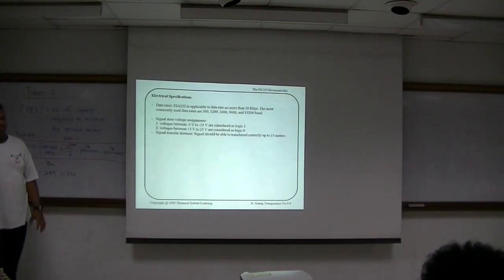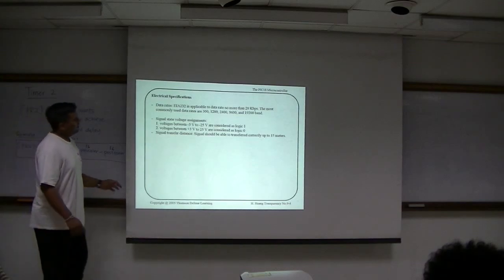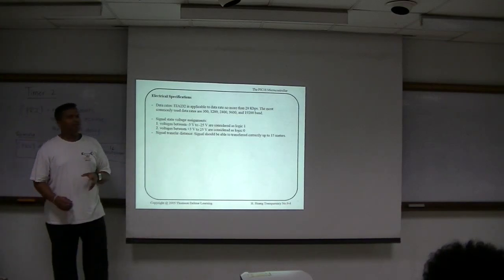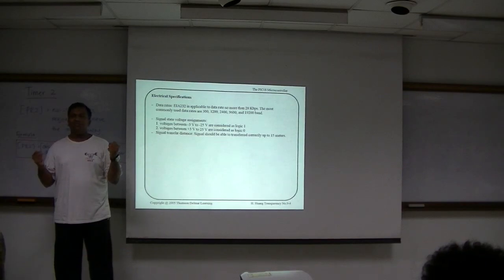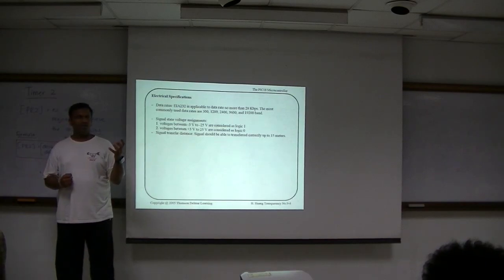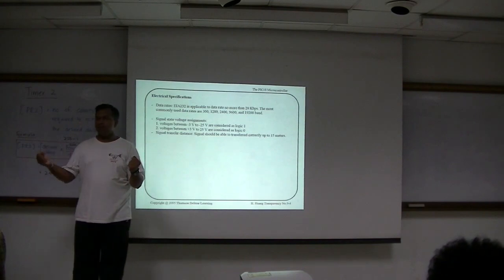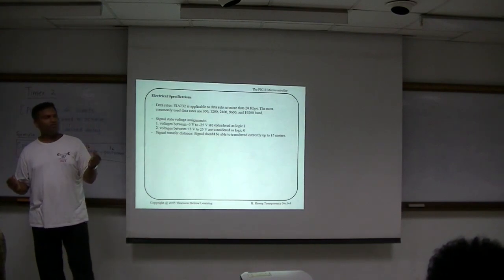Yeah, it's actually 9,600 bits per second. So whenever you see this, it is communication between two devices. Whenever you set the data rate speed, both data rate speeds must be the same. You cannot be transferring one very slow and one very fast. What happens if you send one slow and one fast?